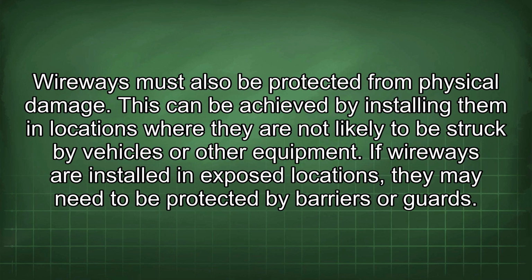Wireways must also be protected from physical damage. This can be achieved by installing them in locations where they are not likely to be struck by vehicles or other equipment. If wireways are installed in exposed locations, they may need to be protected by barriers or guards.